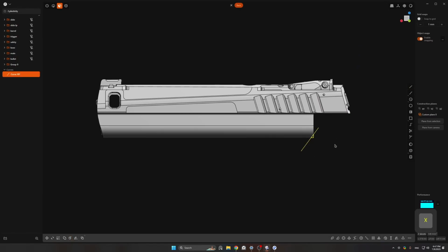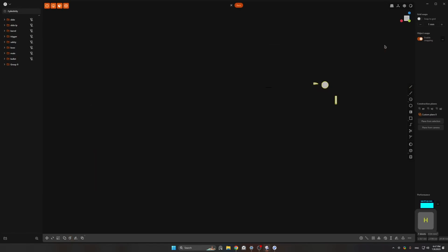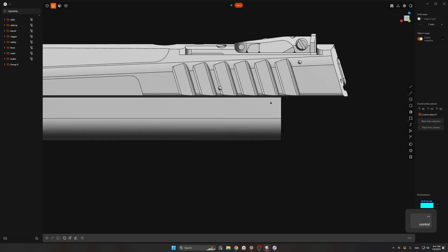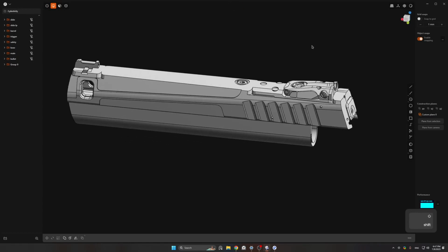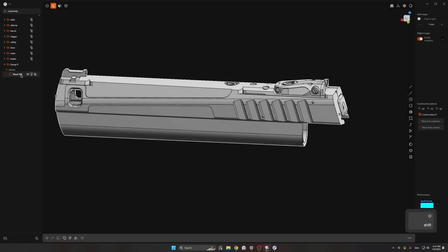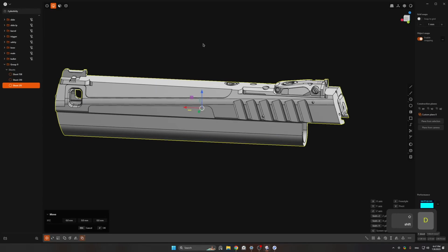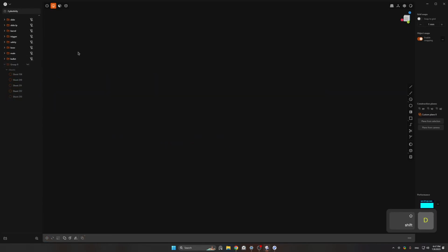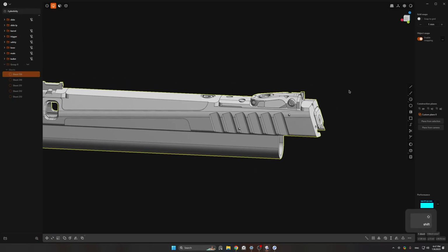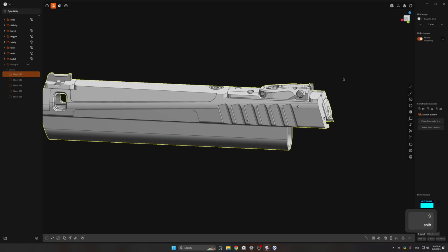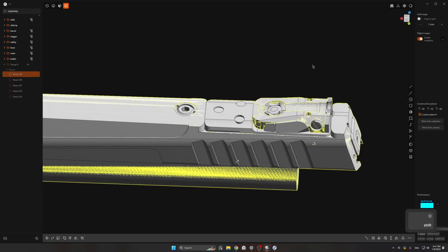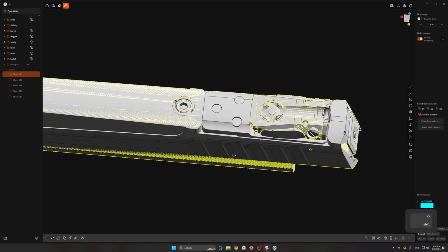Now cut it anywhere to force the recalculation, because we might have some cavities inside that didn't split when we deleted a face to turn it into a sheet body. Now let's duplicate it a couple of times. Let's hide the folder with them. And we're gonna first select our union sheet, and then we're gonna select details that do not touch each other on the surface.